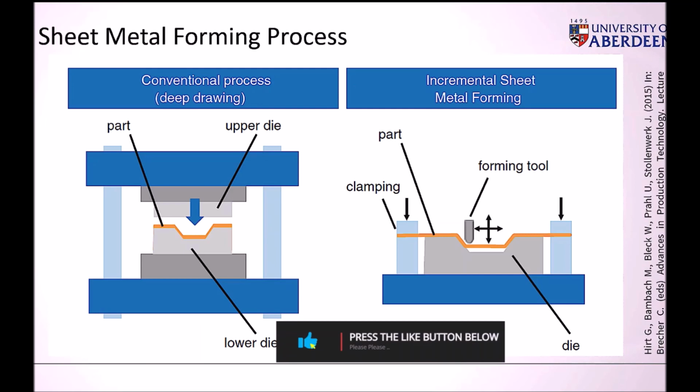These are some of the examples. As you see, this is a microstructure level failure. You can see how the failure really goes along the microstructure with nucleation and growth. And this is actually a test we have done in the past, and I will show you the example later on, the Nakajima test, to find out the forming limit. This is a test at macro scale, and we try to compare it with our model at micro scale as well. These are some of the examples I've shown here.